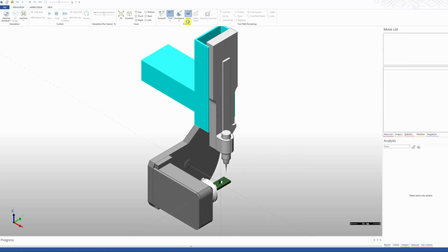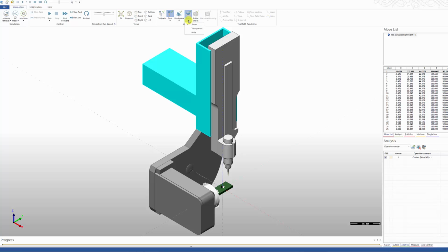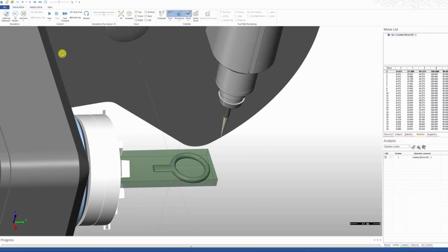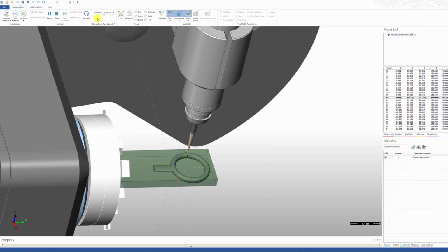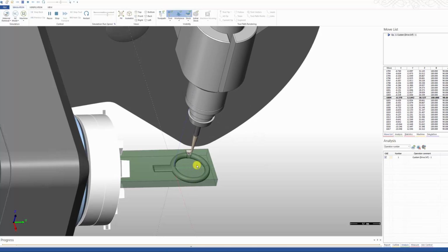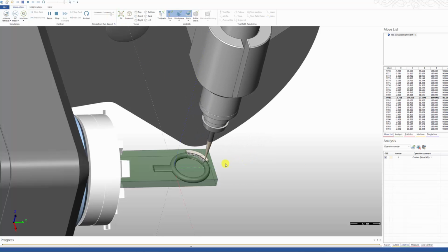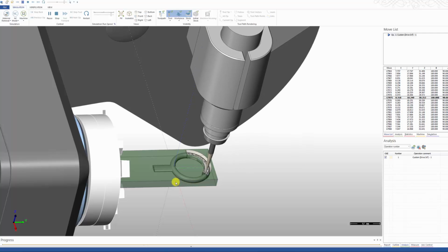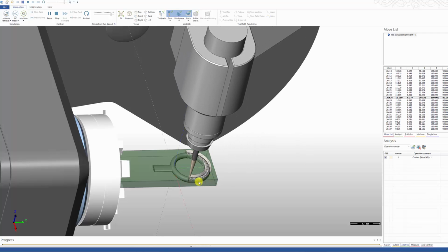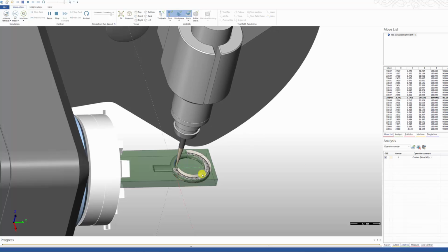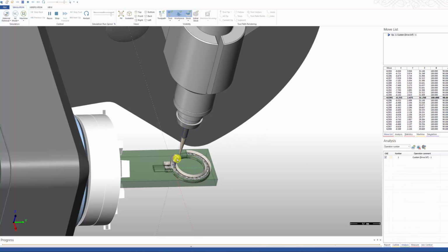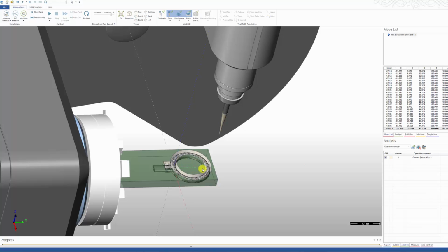As you probably remember, using our boundary curves, we cut the entire piece, including inside. Here, you will notice it does something different. Instead of going across and cutting out this middle part, it will simply follow the outline of the geometry, or to be more precise, it will follow the outline of the drive surface, and it will only cut that, excluding anything outside or inside of it.